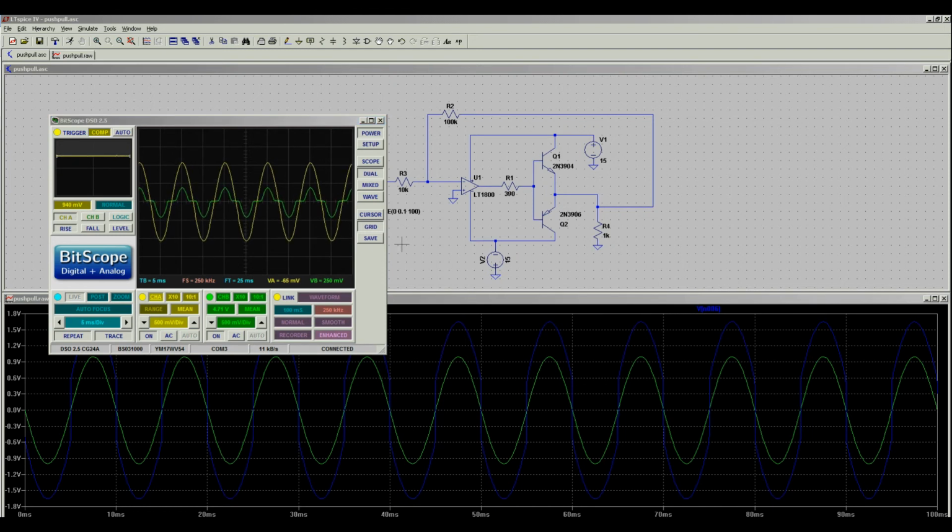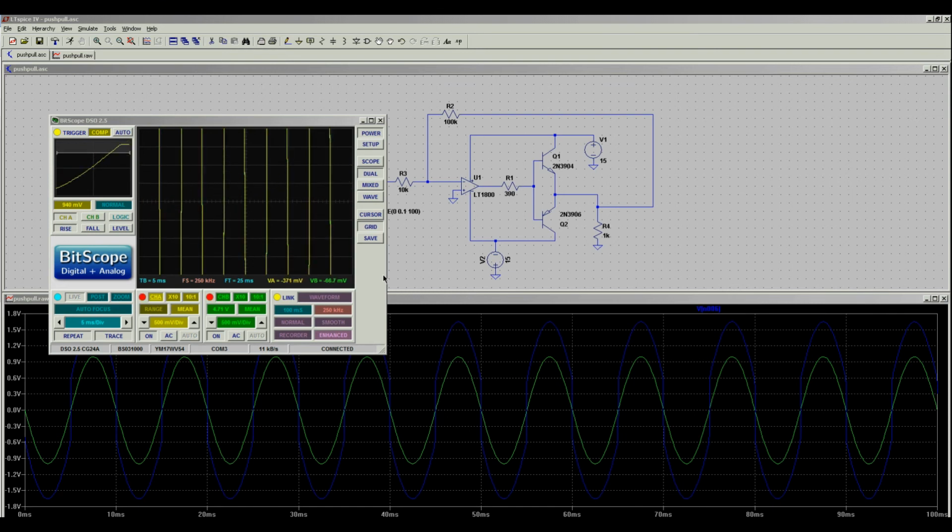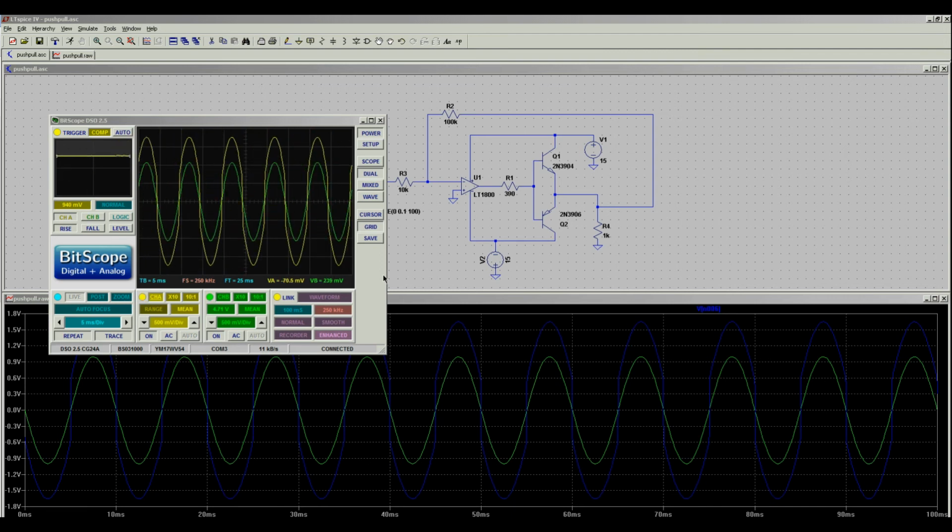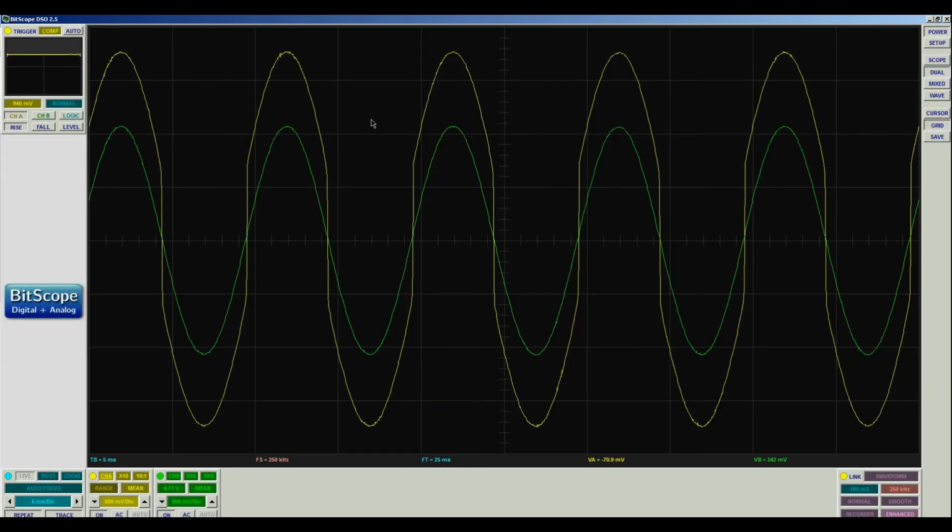I'm going to go ahead and move the resistor on the breadboard from op-amp output to the power stage output, and let's see what happens. So I pulled it and I connected it, and we can now see that the circuit is working very close to the simulator.